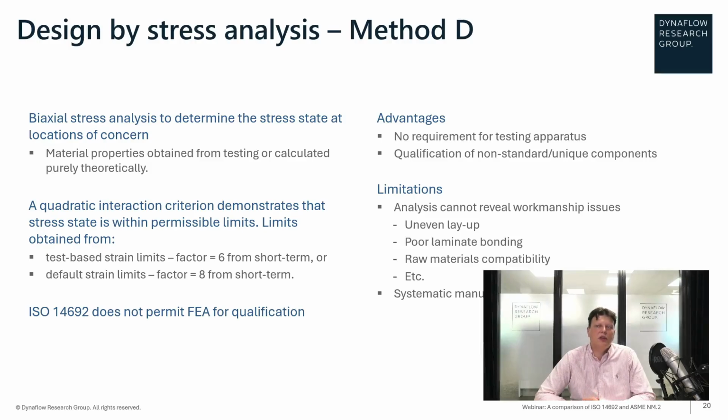And of course, sometimes there are geometries or complex, unique constructions that cannot be easily qualified or tested, and FEA does have some use in this context. So in general, more complex methods to evaluate stress are generally a positive addition, and writing that in the code or facilitating the qualification of these more unique components through FEA is a good thing.